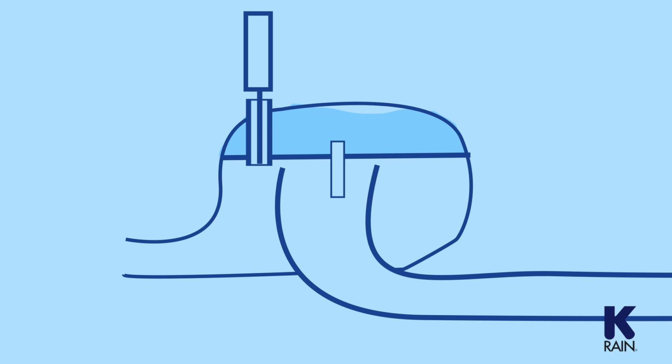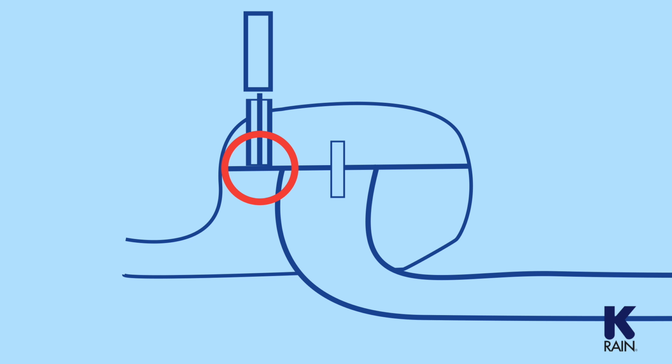Once the chamber is full, the water puts pressure onto the larger surface area on top of the diaphragm, causing it to close again. When there are valve problems, the body of the valve usually isn't the problem, but the internal components that do the work to make the valve open and close. The plunger, which must move freely up or down. The exhaust port, which must open and close without clogs or damage and allow the plunger to seat securely. The metering system, which must remain open to allow water to flow into the upper chamber of the valve. The diaphragm, which must seal properly.